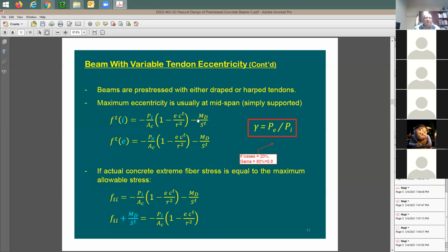So you'd like to use this beam efficiently. You know, when you do a beam design, let's say in conventional concrete, just to give you here an example of how we do it, you have two ways of doing this. It is either that you can assume you can throw there some reinforcing, and then you figure out phi Mn, you compare it with M sub U. This is one way. Another way, you set the capacity equal to the demand, and then you figure how much AS is needed. Does this make sense or no?